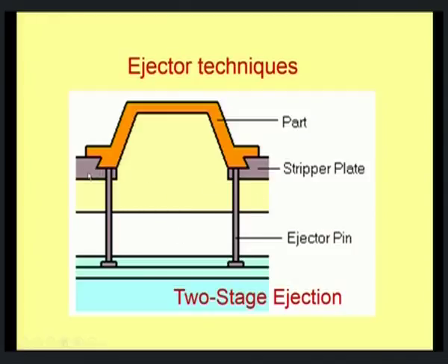where first the ejector plate moves the part up, and finally here, this is what is an undercut. Now the part that is just adhering to this, as the ejector plate moves up, the part will not remove easily with respect to this region as well as this region. Now once the ejector plate moves the part out, next the ejection pin would again push the part out, thereby reducing the release resistance that is being offered here as well as here.